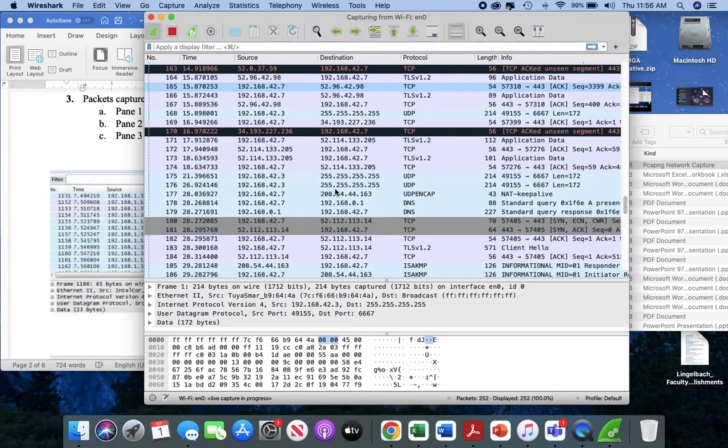Okay. So it wants you to do wired so we can see the Modbus and TCP traffic. So I'm going to stop this, and then you can do either a file save and save that packet capture, and then give it a file name and save it on your desktop, on a server, or wherever you have your, if you're a network administrator, wherever you save your packets to.